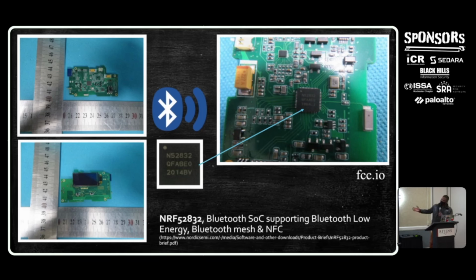I get to see the type of chip that was being used, and along with some of the other reports, you can just get a good visual and look for potential debug ports like UART. In this case, those in particular are not applicable, but I got a lot of information without ever touching the device, as you'll see moving forward.